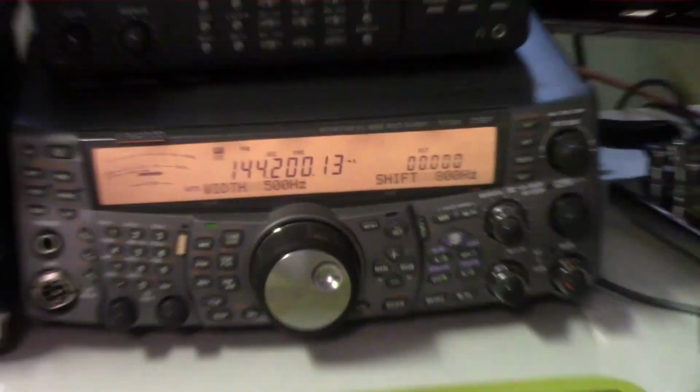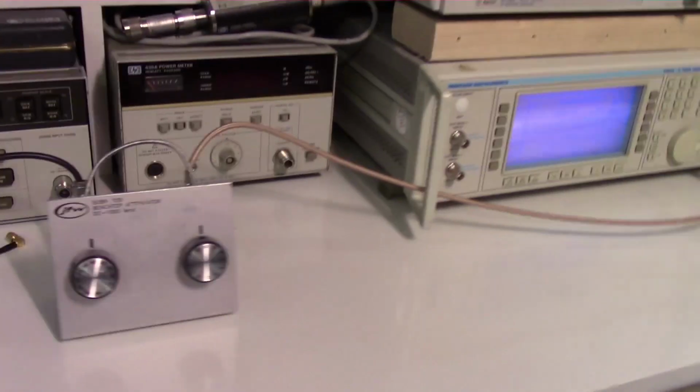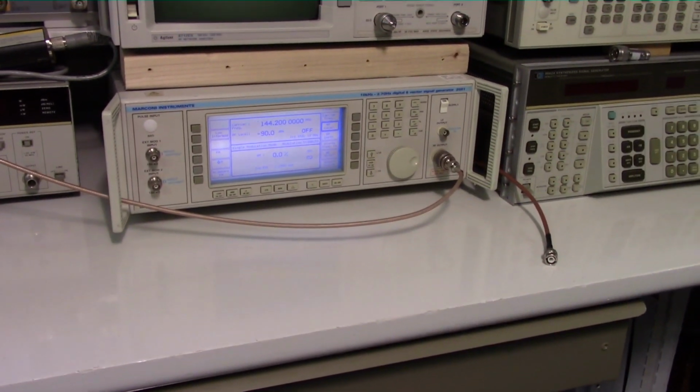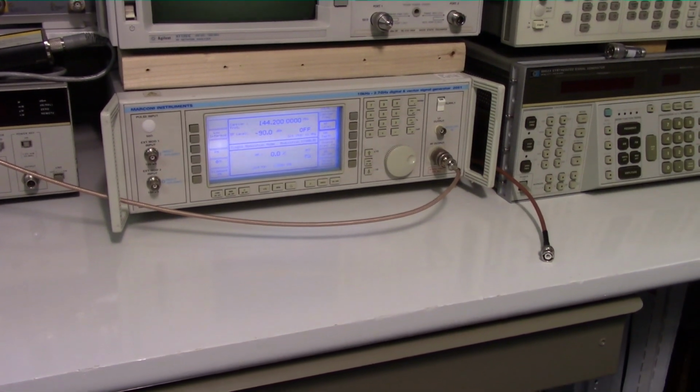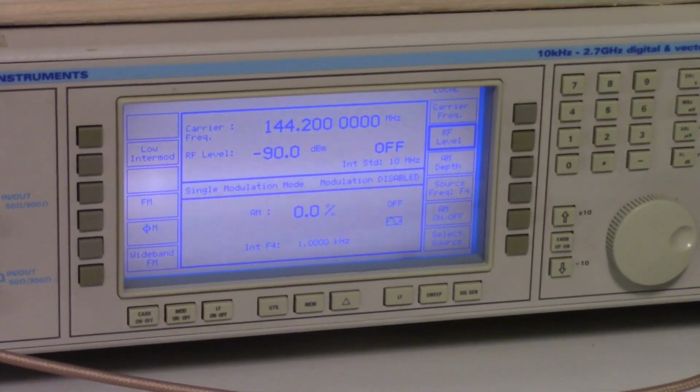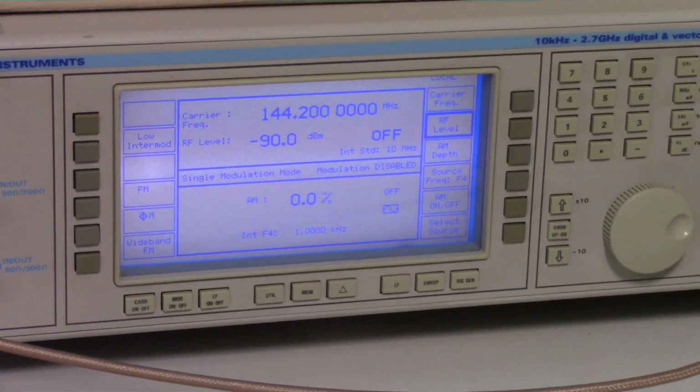Now that we found it, I'm going to go ahead and turn this level down. We don't need to be listening to that background noise. I'm going to pan over here. Now that we found the RF signal level that resulted in a 3 dB delta with the carrier on and off, all we have to do is calculate what the absolute RF signal level going to the receiver was.